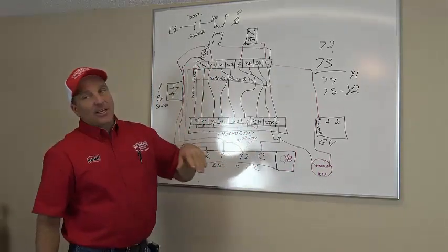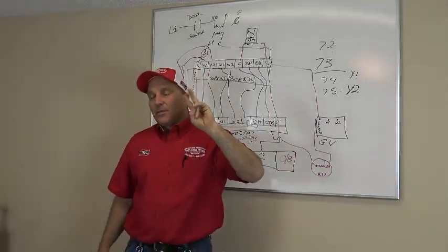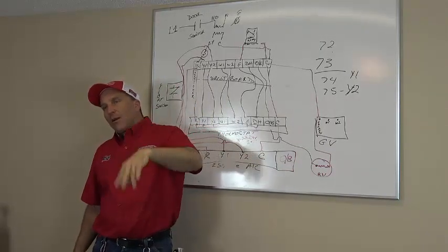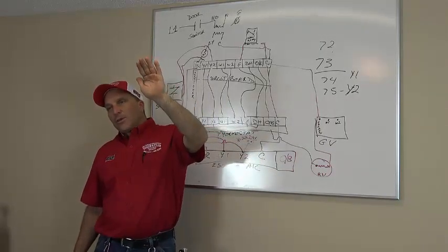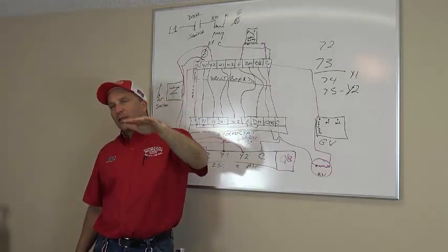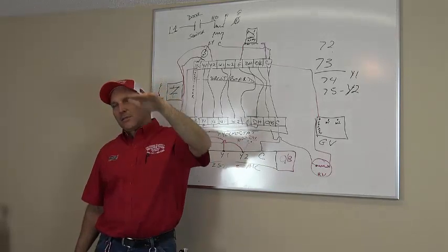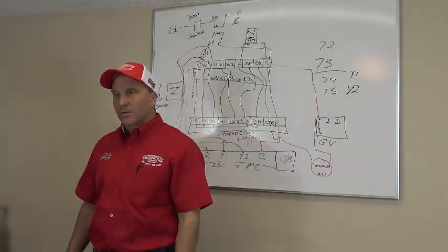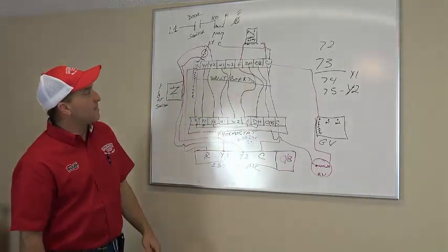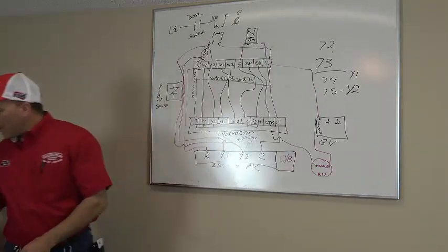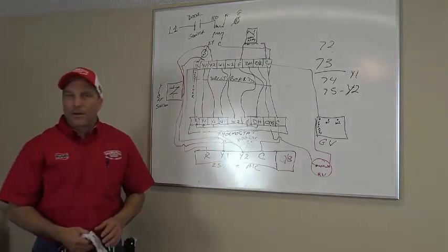So first stage kicks in at 1 degree below temperature. The second stage kicks in at 2 degrees below temperature. Okay? And then it warms the house back up to whatever temperature you have it set at, shuts the system off, boom, cools back down. First stage kicks back on, heats it back up, and stays within 1 to 2 degrees. Okay? That's the way your heating system works. Everybody understand that? Alright? Anybody not understand what we got right here so far?